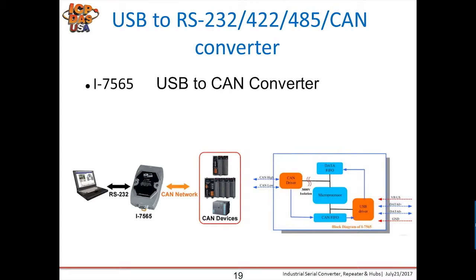The i7565 is a cost-effective device for coupling the CAN bus to PC using a standard USB interface. The interface is present in every new PC and is supported by Microsoft Windows 98 to Windows 7 operation system. If you establish the connection between i7565 and the PC during the runtime, the computer will automatically load the relevant device driver.